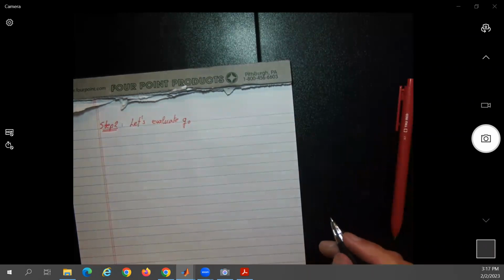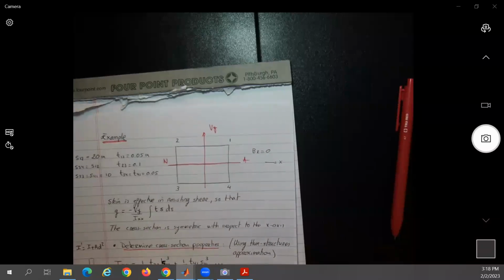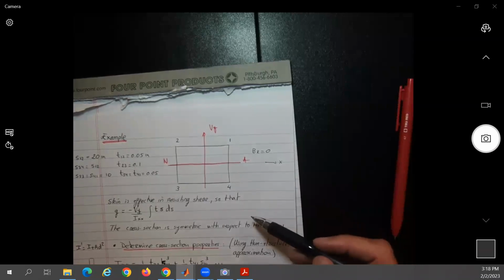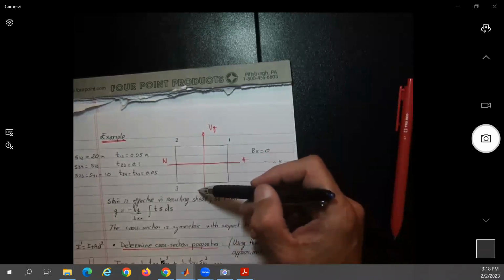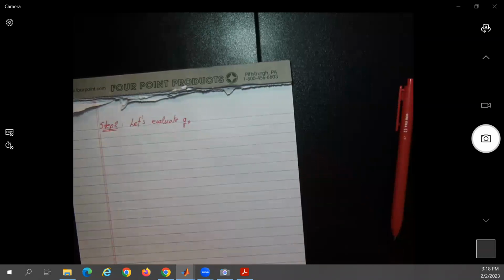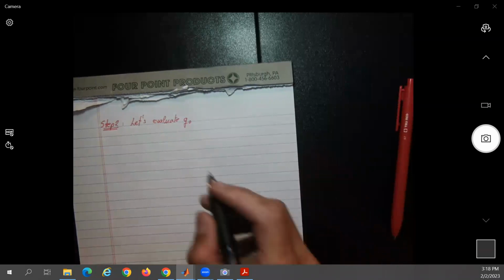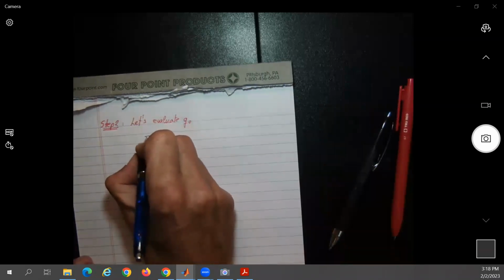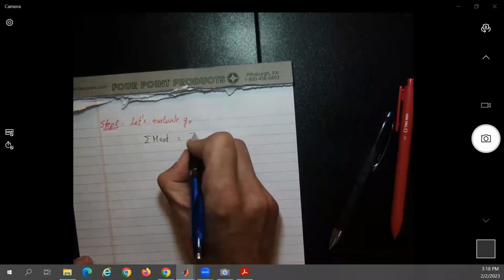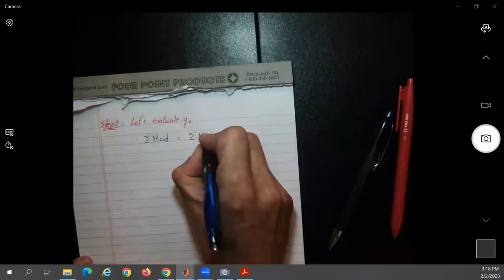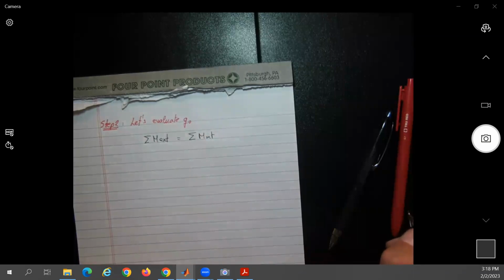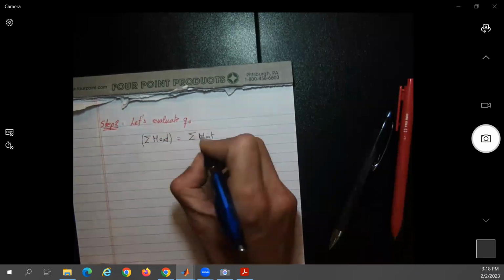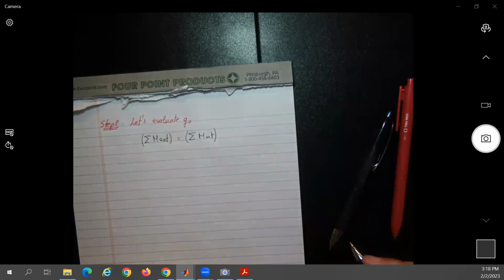Okay, so in order to do that, what did we do before? Oh, first, this problem is it statically determinated or indeterminated? This one would be statically determinated, no? Okay, if we add one other section that is not needed, it would be indeterminated. So in this case, when we do this, instead of you doing the same angle of twist, and then the moment, we only need to use one equation. Let's do summation of external moments be equal to the summation of internal moment. Okay? No matter what, I'm going to finish this problem. So, to simplify the process.